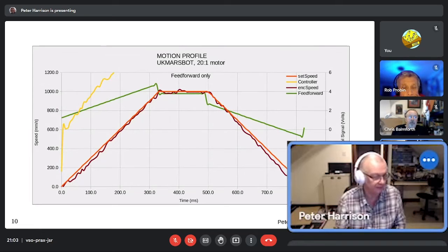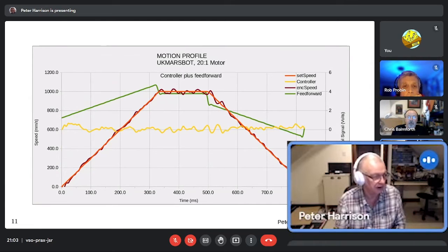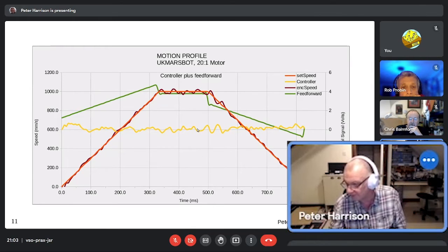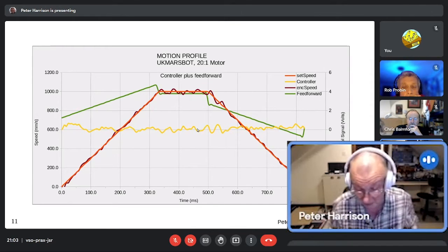Whoops, gone too far, as usual. The response I'm looking for, if you've got your feed forward and your feedback controller set up right, then for a simple run, if your controller output is close to zero all the way through, that's how you know that you've got it right. And I couldn't get it right. I couldn't for the life of me work it out.